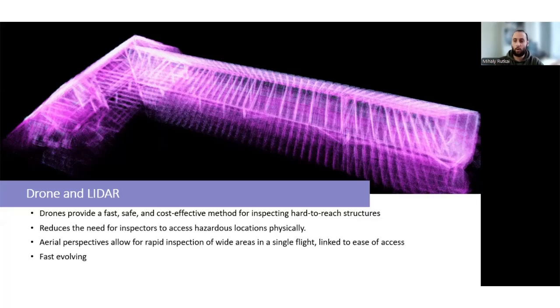With the clarity of the drone camera, cracks, knots, and many other defects could easily be reported from the comfort of an office. Meanwhile, the LiDAR allowed for measurement and general survey of the area to be able to even count every timber rafter, post, and batten.